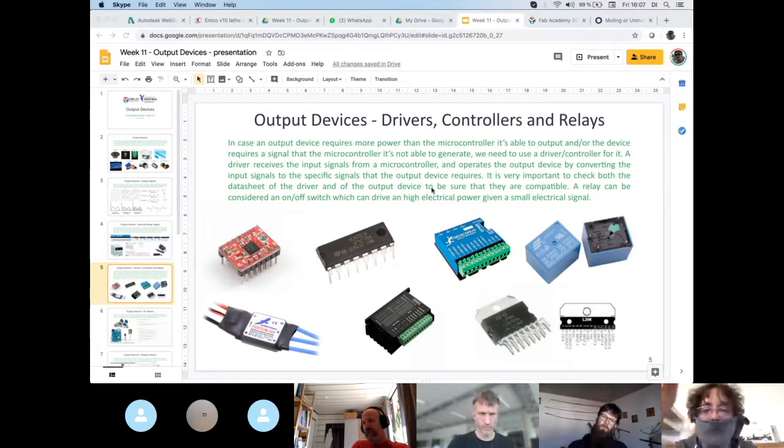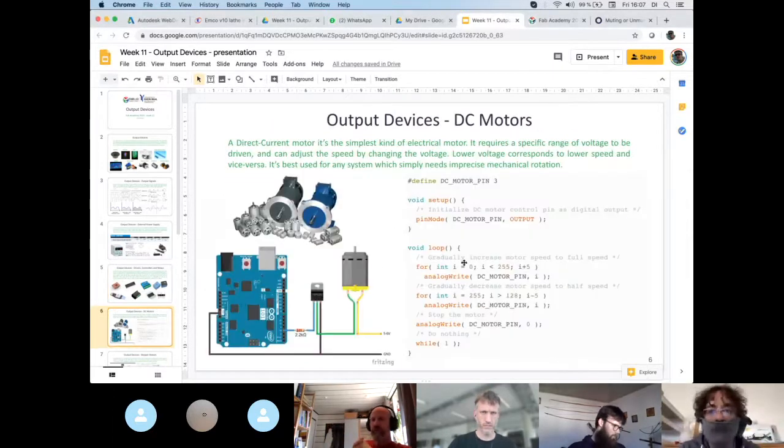The voltage is going to be adjusted by the transistor or the MOSFET, and the transistor or the MOSFET takes as an input the pulse width modulation, the PWM. So I run the PWM into my transistor, which is then switching at the same speed. So essentially, I'm switching a high voltage PWM, right? You have to input a PWM signal, as in this schema that you see here, to the transistor, and then the transistor will vary its own internal resistance to vary the voltage.